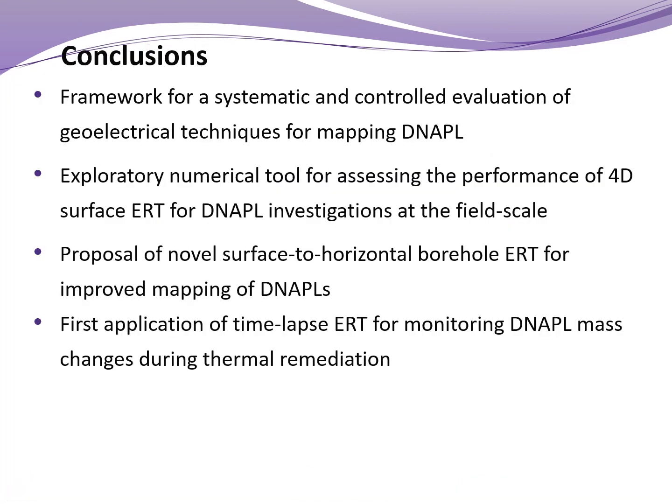So the conclusions: you've seen a framework for a systematic and controlled approach for evaluating ERT for mapping DNAPLs. I've shown you a new exploratory tool for assessing time-lapse ERT of DNAPLs at the field scale. You've seen the proposal of a new surface to horizontal borehole ERT configuration to enhance ERT performance, and also the application of time-lapse ERT for monitoring DNAPL mass reduction at a field site.